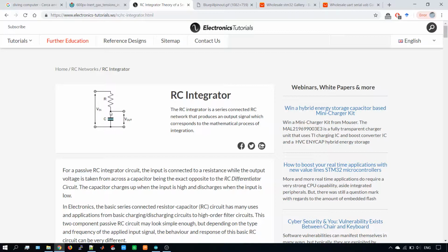So I have the voltage in and the capacitor, the central point, to connect to analog inputs, and this is the ground and this is the plus 3.3 volts. So I can measure the voltage in the V in and the voltage in the V out.